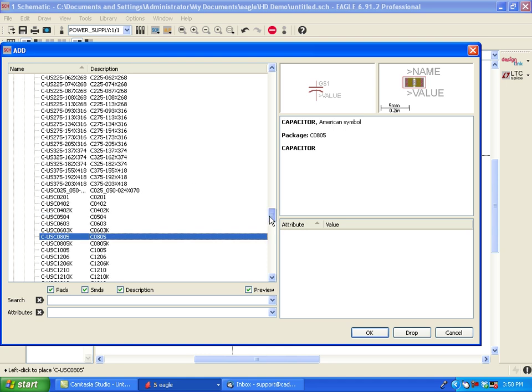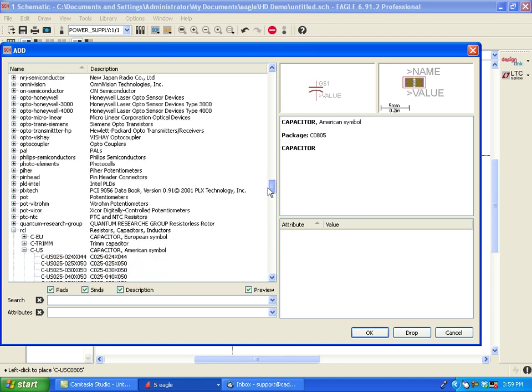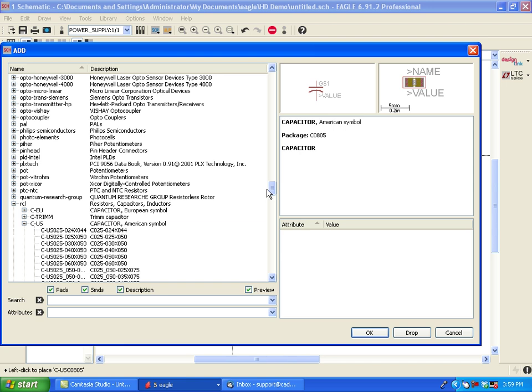I'm going to go ahead and now put in supply symbols. Within modules, the scope of a supply symbol is that very module. It won't extend outside to the higher level of the hierarchy. Okay, so keep that in mind. When you use a supply symbol within a module, it's going to be restricted. Its influence or its scope is going to be restricted to that module. Important thing to keep in mind.